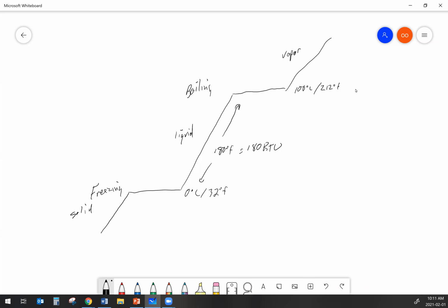And then, once that water is all steam, we can continue to heat it up afterwards. But that point in time where that liquid water was boiling, where we're busy adding heat energy to that water but not seeing a rise in sensible temperature, that's called the latent heat of vaporization. It's where you're putting heat energy into something, but you're not seeing a change in temperature. That's latent heat.